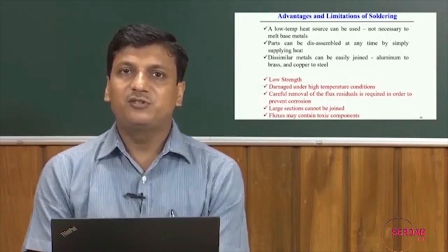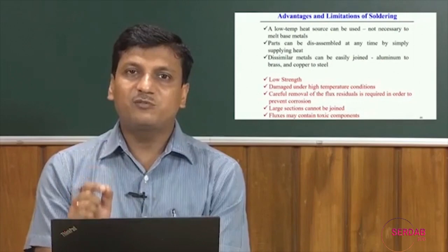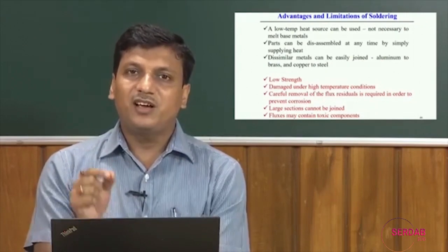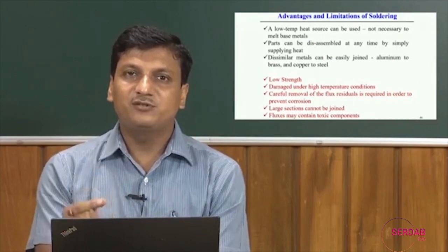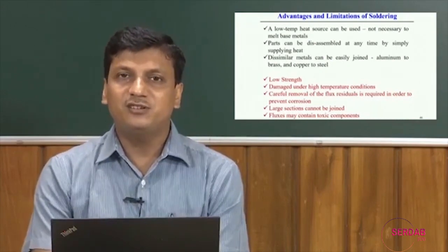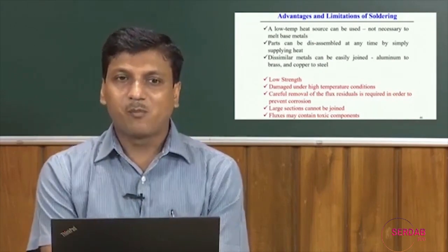So we try to localize the heat application, and the heat intensity should be low enough that the temperature is controlled below 450 degrees centigrade.